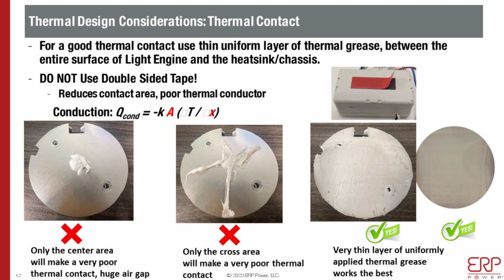So as you can see on this picture, although I have a driver, notice the total surface that is available to conduct heat away. Number one, you're using only maybe 20% of it. And secondly, it is a thick layer. Notice again this conduction equation. Area is dramatically reduced, let's say you're using only 20%, and the distance is also increased, and the K factor, which is how conductive it is, is also poor. So your conduction, or the amount of heat transferred, is going to be dramatically lowered.